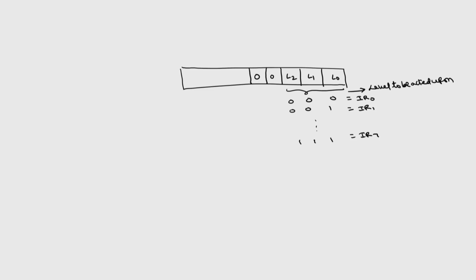And the next 3 bits are going to decide the mode. This is called R bit, rotation, it is going to decide the rotation, then SL bit, EOI bit, and this is of course A0 bit which is 1, so these are D0 to D7.